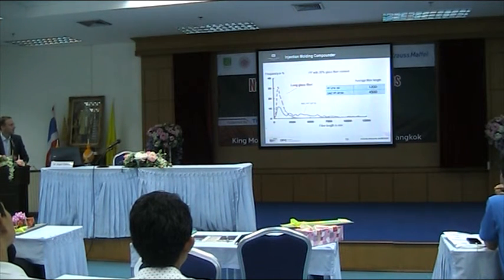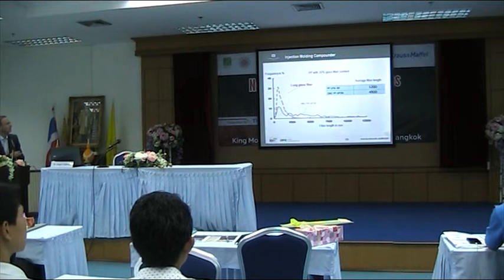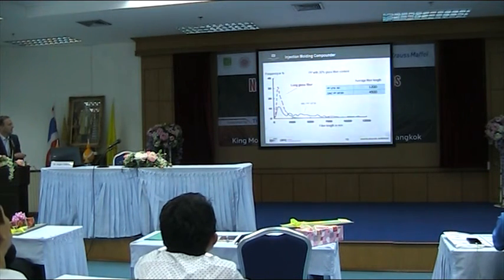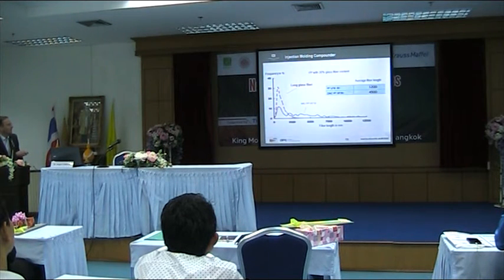So here you see for injection molding compounder, but for glass fibers, a typical fiber length distribution over the frequency. So how often it is. You see, with the classical long fiber injection molding process, you have fibers especially in the area of 0.5 till 1 millimeters, and then you have really a sharp distribution of fiber length. And with the injection molding compounder, you can reach a higher amount of longer fibers.